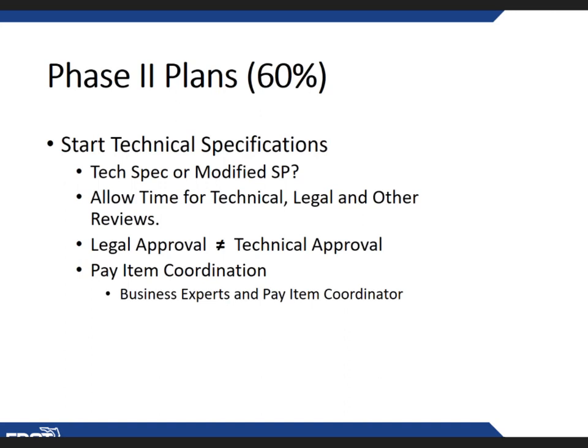But when you have steep slopes, the error in a plan view versus something laying along the slope may be 8, 10, 11%, and that's where you start getting into claims and overruns and all kinds of problems. So the specification under... we'll talk a little bit about specs here later on.